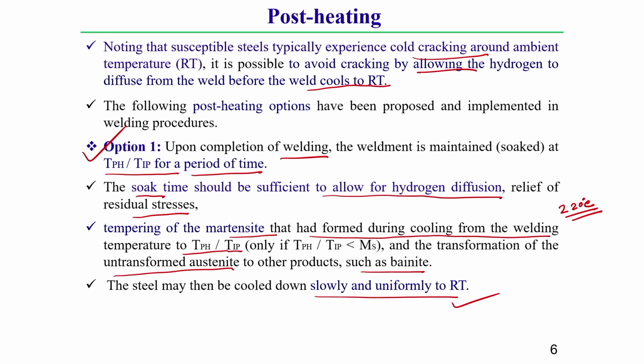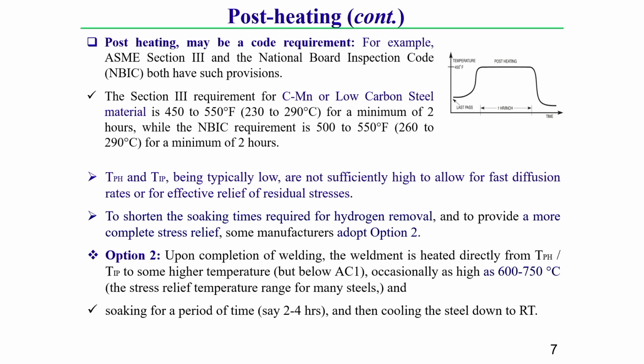But here one thing you can observe, that the post heating temperature is comparatively less. For this post heating purpose, there may be a code requirement. For example, ASME Section 3 and NBIC, the full form of NBIC is National Board Inspection Code, both have such provision.